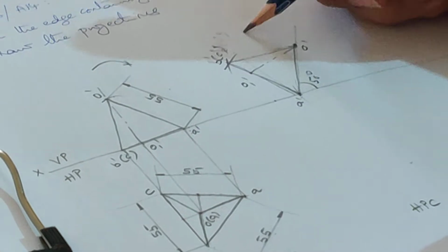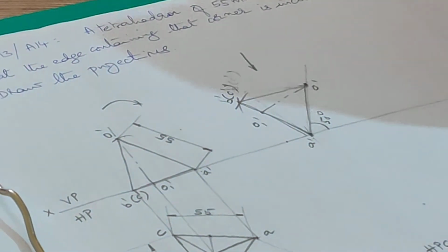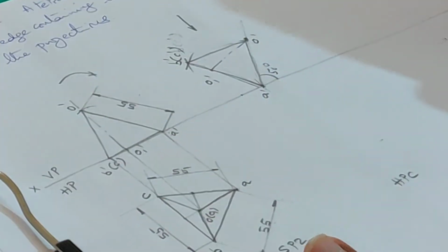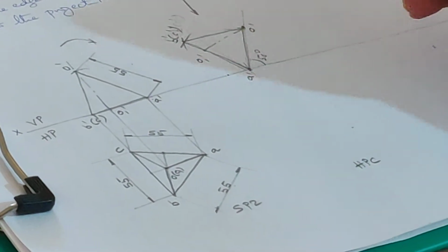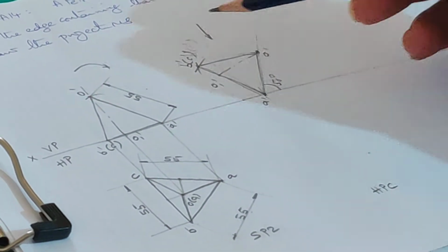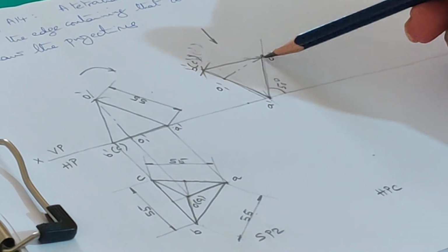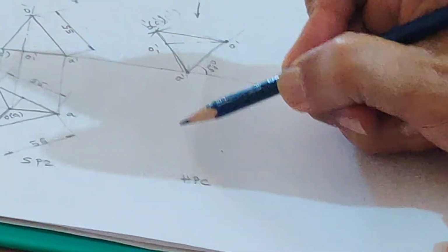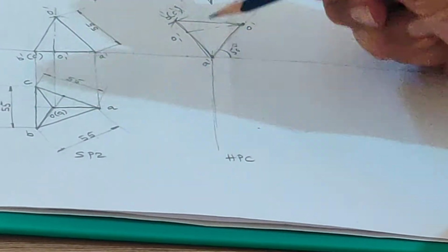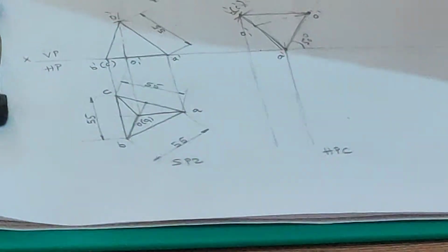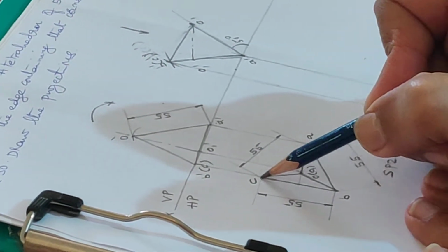Now let us apply the rules of visibility to this view to get the top view. The rules of visibility are similar to the pyramids you had. Now if you look at the base of the pyramid or the base of the tetrahedron, it is away from the observer. Apex is nearer, base is away. So the observer will not be able to view the base. So you cannot draw all the three base edges visible when you draw the top view. Let us draw the locus lines.